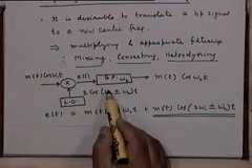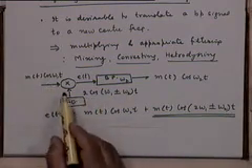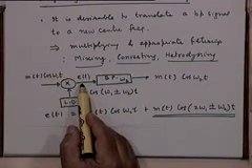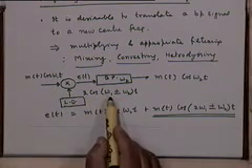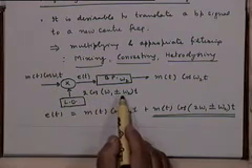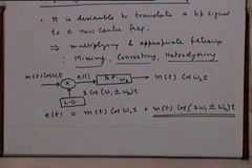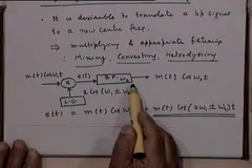Think carefully. Basically, what you have to look at is the frequency argument. What will be the frequency components that you will have here? Omega 1 plus 2 omega 2 minus omega 1 plus omega 2, and of course the sum component. The sum component we don't have to worry about. And what is this equal to? Omega 2 again. So this will also be passed by this band pass filter, right?